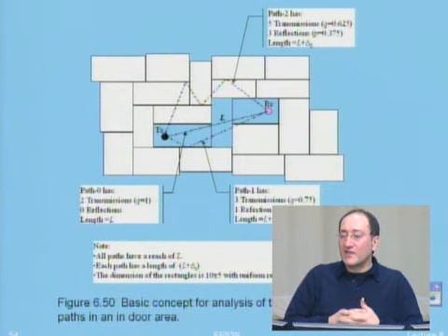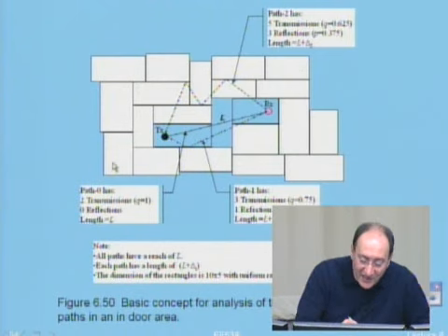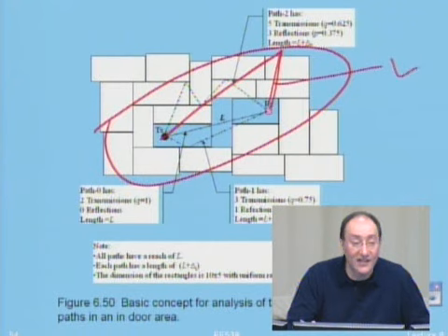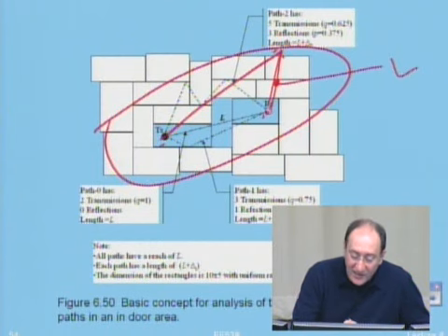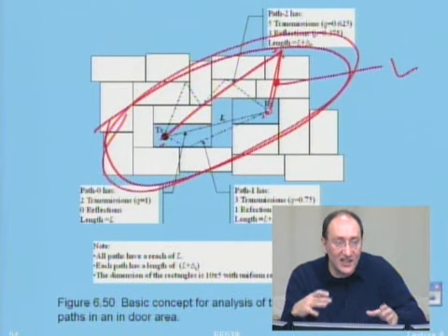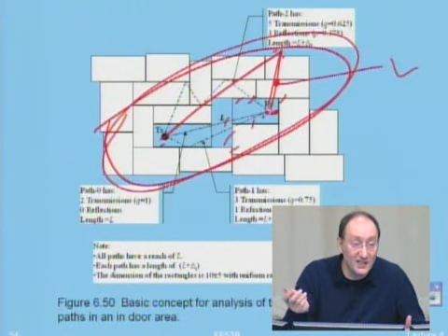What you say is that my coverage is like so much, so I take an ellipse around here. An ellipse, if you remember, has the property that this distance plus this distance is constant, like L. And this is like a path. If the path loss associated with this is like 30 dB, I can sketch an ellipse around this as the area that I stay in. Then based on the density of the walls, I can develop some statistical models.